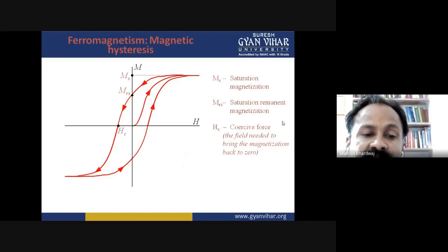The other types of ferrites are used as permanent magnets. Ferrites for soft magnetic applications are mixed ferrites having in their composition metals like these. Some ferrites possess the hysteresis loop shown in the slide, which have been used earlier. Still other ferrites are used as components of electronic devices, microwave devices, and magnetic computers. For memory and switching devices, these materials are used in the form of thin films.